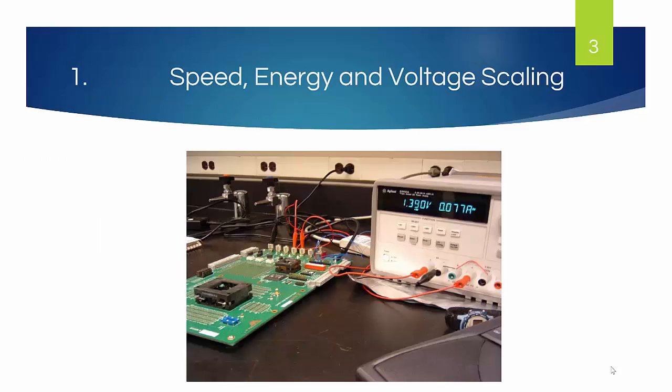Razor is a specific technique in the area of dynamic voltage scaling and is based on detection and correction of circuit timing errors. This allows design optimization that tunes the energy in a microprocessor pipeline within typical circuit operational levels.